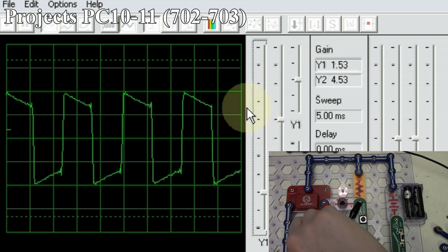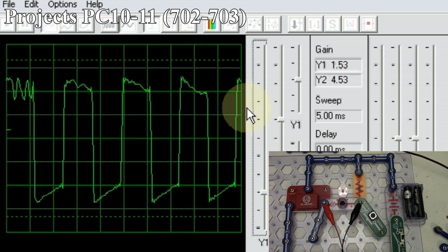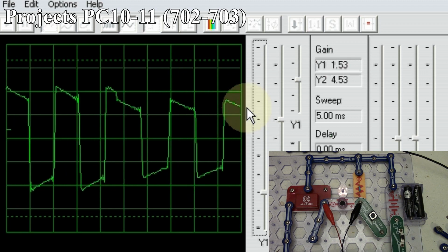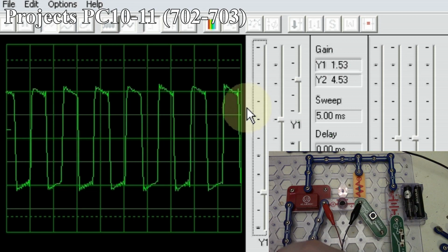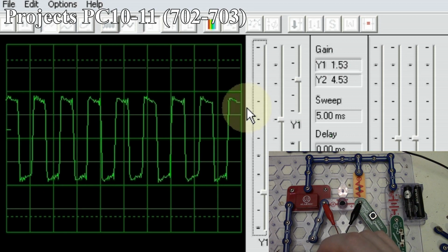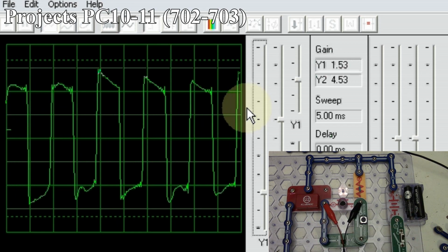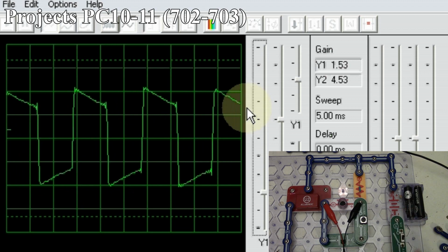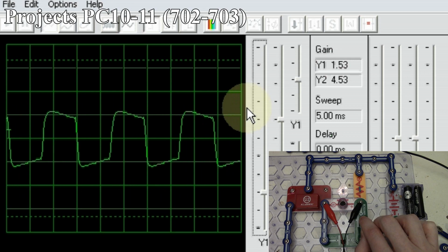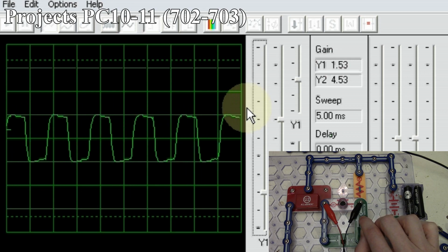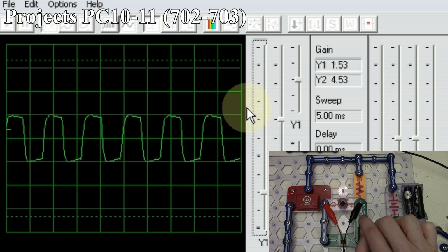Now, of course, the whistle chip is an example of a small capacitor. What we're going to do here is put an actual capacitor in, which is our C1, our 0.02 microfarad capacitor. Just this run right here. And this provides some true capacitance to the circuit. So when we put that in there, we won't hear anything, but if I hold our switch there, you can see we still got that nice rounding on our waveform, so it's acting as a noise filter.